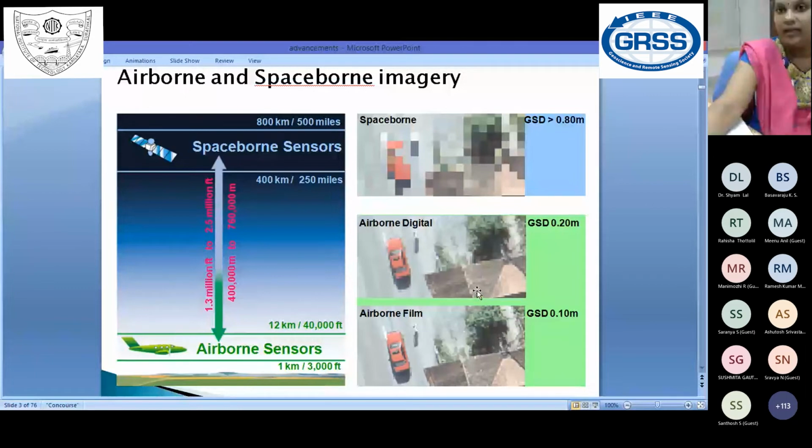So we have nowadays Sentinel data of 8 meters, 10 meters. If I want to do some classification for some application, like I want to identify the land use land cover class, that's all, then I can use an 8 meter resolution and generate a land use land cover map, a thematic map showing built-up area, a group of buildings, roads, something like that. But in case you want each individual building, then you need to go for higher resolution.